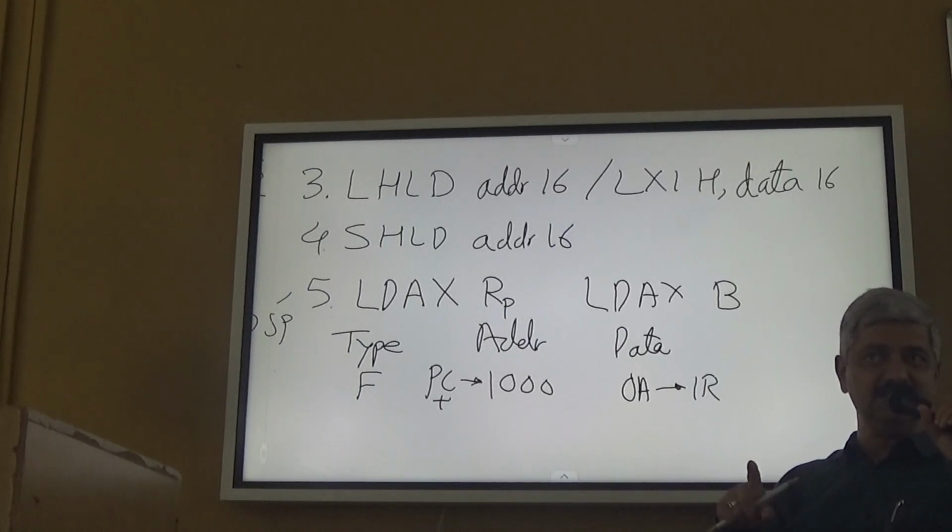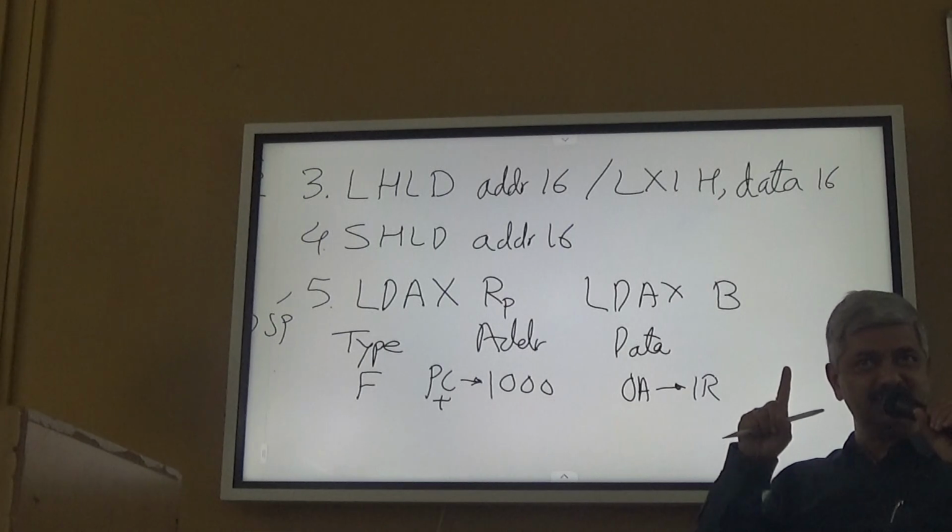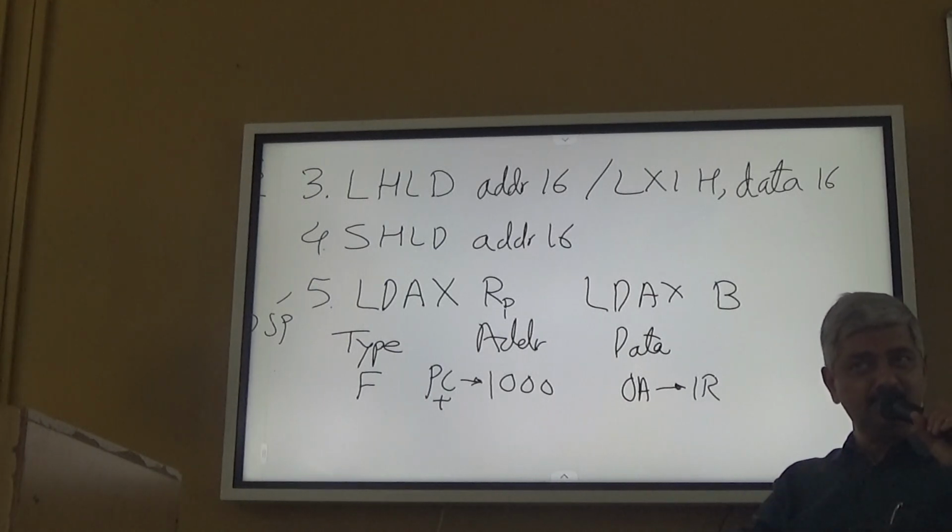The instruction requires the microprocessor to bring the contents of an external memory location into the accumulator. So the operand is external. Therefore, for execution only an additional machine cycle is needed.